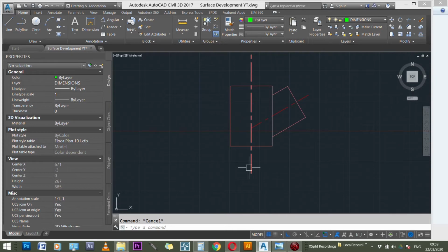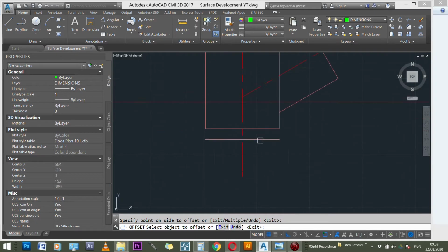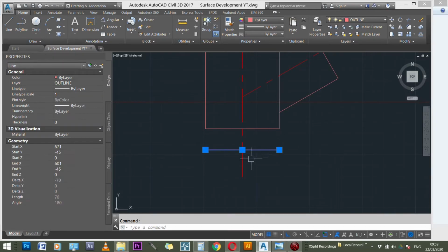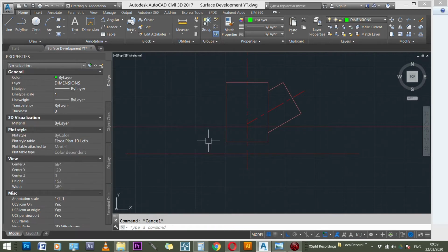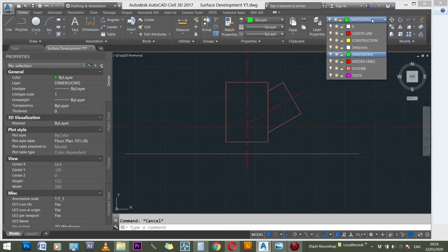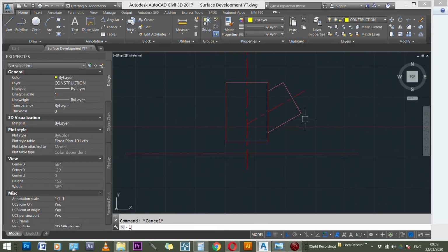What I like to do is offset 10 millimeters from each joint. I just offset 20, make it 20 millimeters between joints, and I create what I call my frame lines so that I know this joint is finished, nothing is going to be around here. So now we are proceeding to the next joint, and the next joint we are going to be starting is